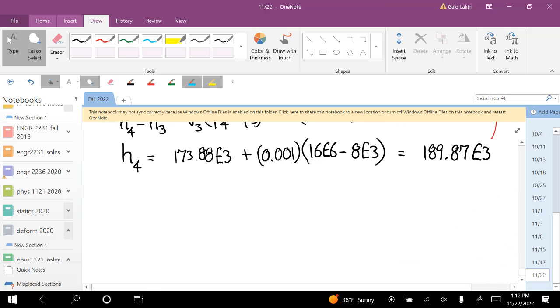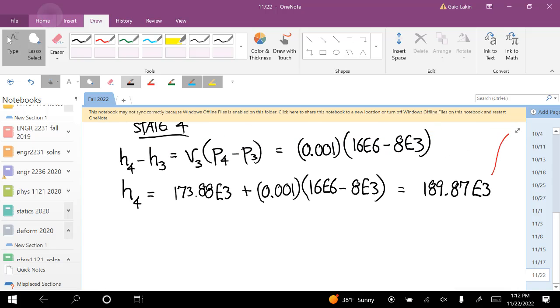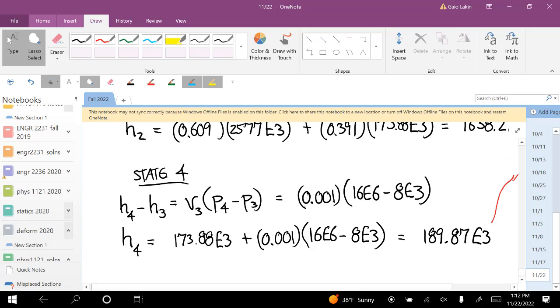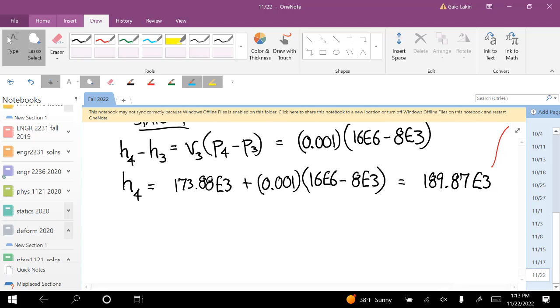That's funny. So, I was doing it with the condenser pressure only half as big as the boiler pressure. Yeah, and so I got this horrible efficiency and stuff. I'm like, oh, that's weird. That's what I was about to ask, was your efficiency super low then? Yeah. Okay, but anyways, now we went through the same exact steps as last time, got the same 4 enthalpies, and now it asks us roughly the same questions with some differences.